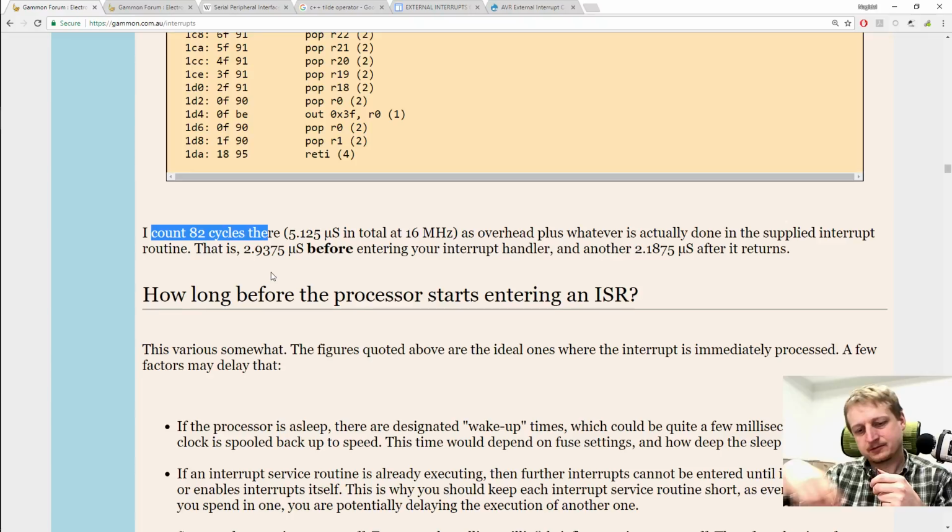But a DC motor, once it runs, that's the whole idea, that I want to have a DC motor running all the time. That's why I'm doing the thing with the axles and those arms tapping. That's the whole idea. I could have used servos, of course, and it would be much easier using servos all the way, even for the 10 grinding tappers. But their lifetime would be very much reduced.